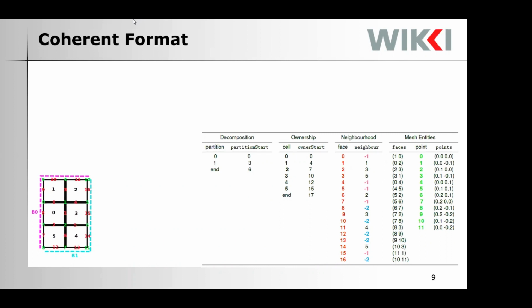What do you want to write? That's an important question. It's some global list present on each rank. Do you want to agglomerate this? That depends. If you want to write on master, just make an OFstream and write on master.